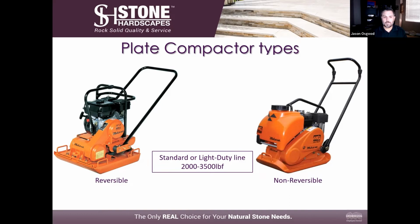Now, you really want to use a compactor that is either a standard or a light duty line. They make these compactors for heavy commercial use. That's not necessary. What you're looking for in a plate compactor for a swimming pool deck or a residential deck is something that's going to have a pound-feet of force between 2,000 and 3,500. That's what it's going to hit. That's how it's going to compact. Somewhere in that range is great. Your vibrations are going to be somewhere between 4,500 and 5,500 vibrations per minute.